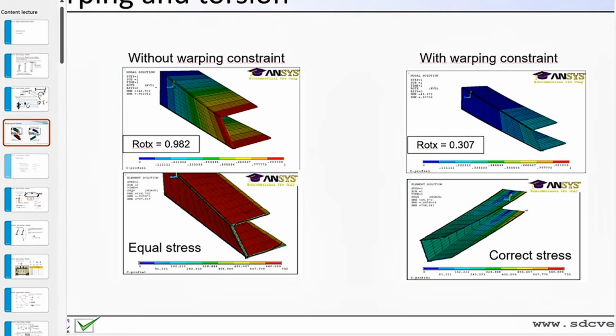In our section, we're going to use limits based on the standard, so this warping effect is taken into account by default there. But if you want to compare this to a linear elastic buckling calculation, be aware that this warping can be crucial.